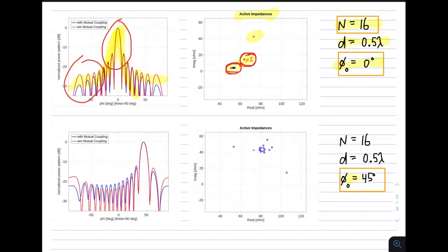So now we'll scan off to 45 degrees. Here is the beam now pointing at 45 degrees. And we see things are getting a little bit jostled up now in the first side lobes, whereas they weren't so much for the broadside pointing. And that jostling is evident throughout the pattern. So there is some difference, especially in the side lobes, but the main lobe is not terribly affected.